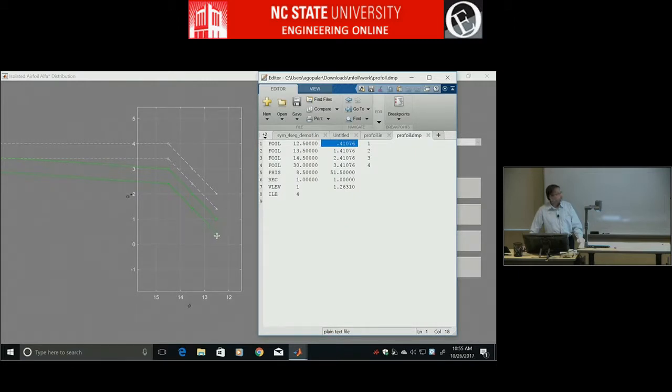We set up that Newton iteration to change alpha stars so that you get a thickness of 18%, and it went and did this. And this is the second segment, third segment. Like that, all the circles are the inputs, the upward triangles are the converged distributions.